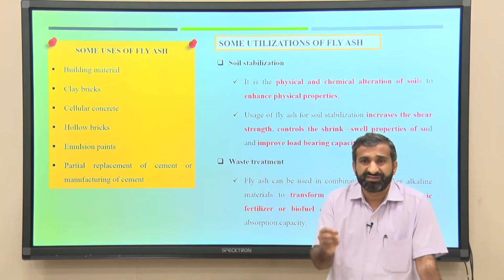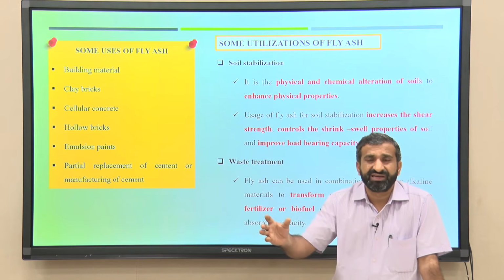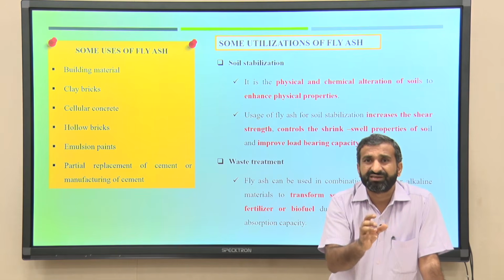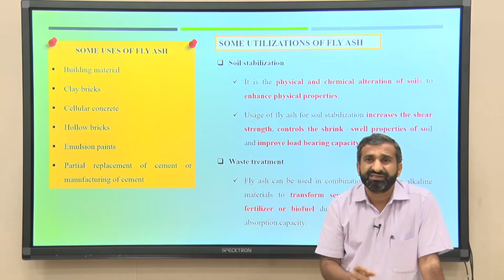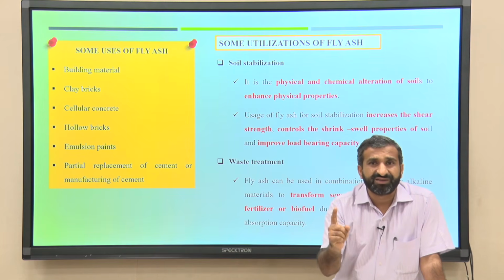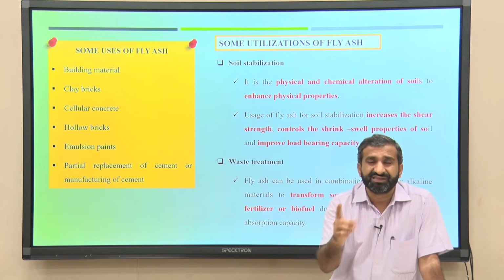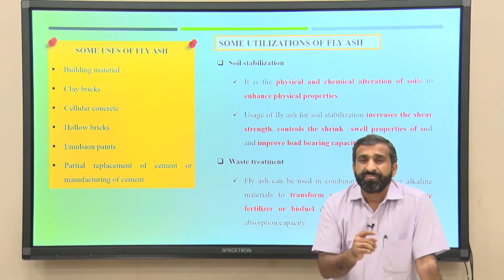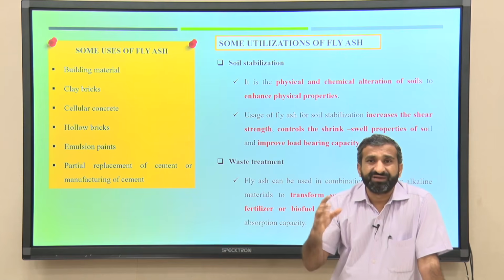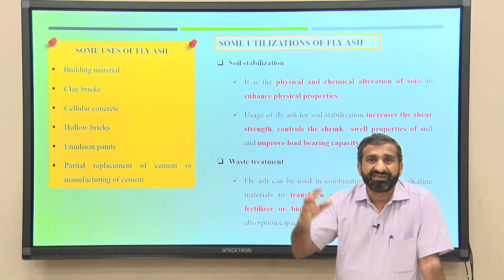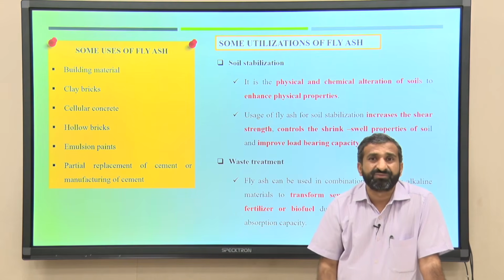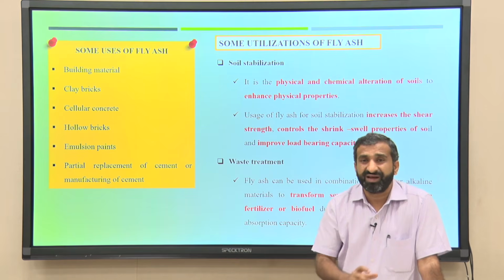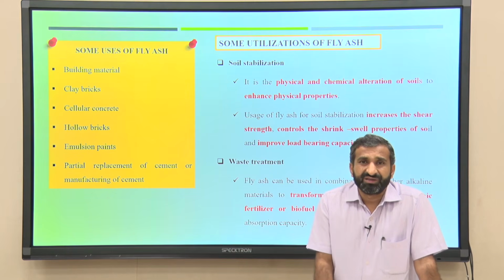Per ton of waste incineration, the bottom ash production is around 100 to 200 kg, or 150 to 300 kg. You understand, for 1 ton of incineration, how much bottom ash is getting produced, and also the fly ash. And suppose the plant capacity is 300 to 500 tons per day. So, you understand how much bottom ash or fly ash is getting produced.